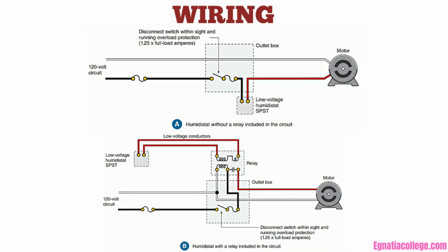Although the example in this residence utilizes a relay to use extra low voltage wiring, it is also proper to install line voltage wiring and use line voltage thermostats and humidity controls. These are becoming very popular, with the switches actually being solid-state speed controllers, permitting operation of the fan at an infinite number of speeds between high and low settings.